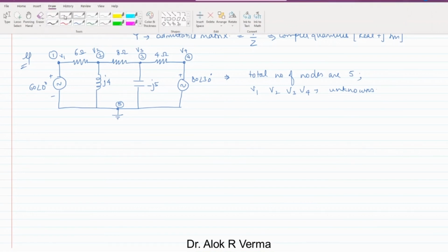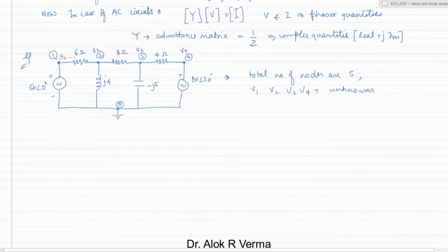So when you convert this, you can clearly see this voltage source and this voltage source, both sides, they are in series with some element, here in this case resistance. But even if it is not resistance, you can convert this in a similar manner when it is replaced by some impedance, like if it is inductance or a combination of R, L and C, that conversion of the source can still be done, but the R will be replaced by the Z.